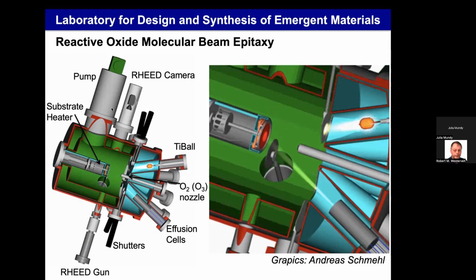This is thermal evaporation, same thing as a puddle evaporating in the sun. But what's really special about this is that we have exquisite control over the temperatures of these various different elemental sources. So we can keep the rate that the atoms evaporate off extremely consistent, in fact, consistent over days while we optimize things. And then right here, you can see that we have a little plate, a little shutter in front, and then we're just opening and closing these shutters, which allows us to controllably deposit one atom plane and then one atom plane, and then one atom plane.